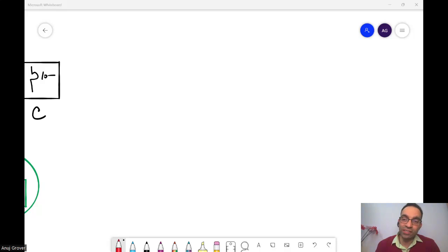Okay, so you are saying that below the latch you add another two NMOSes. Yes sir. Okay, what happens to those NMOSes? So those NMOSes are connected to the bit line, and gates are connected to the bit line and bit line bar. So we will be getting it from there. And like in the capacitor case and in this case, both the memory unit and sense amplifier can operate at different voltages. That's the main advantage in both.